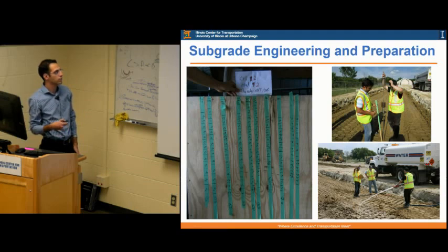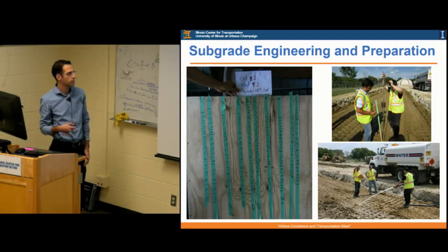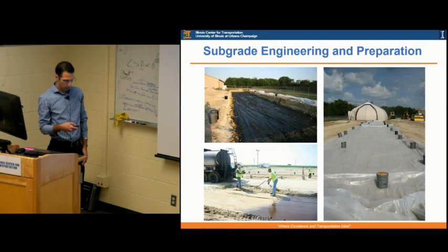That's for a CBR6 subgrade, and that's actually the DCP that we drop at the different locations to get those DCP profiles. And then the wetting of the soil, we calculate the amount of water to add if we need to change that and go through different iterations. This is the sealing of the subgrade after it's ready. That's the CBR1 subgrade, and that's the CBR6 subgrade.